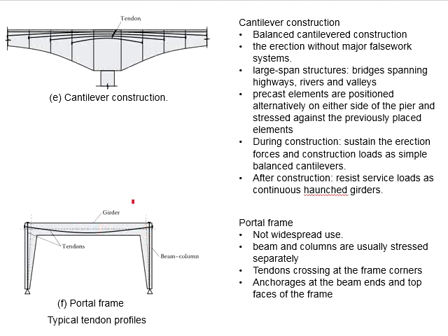You also see that the size of the column here varies along the height. The purpose here is to generate the eccentricity by adjusting the central axis of the column so that it becomes negative eccentricity at the end of the column.